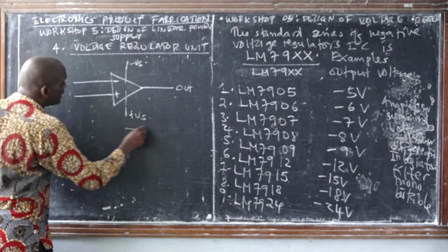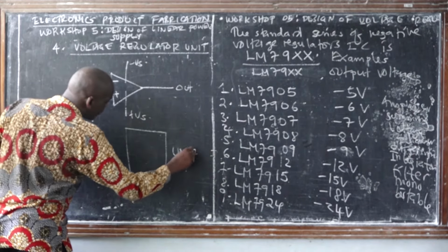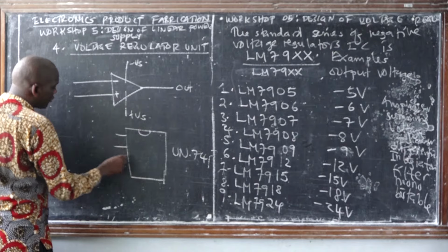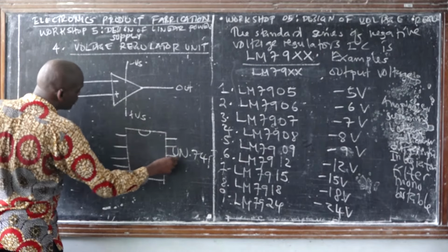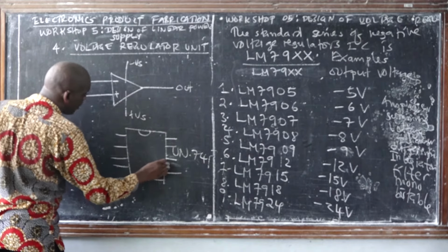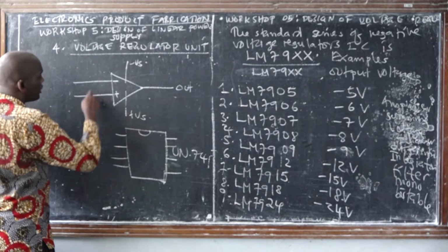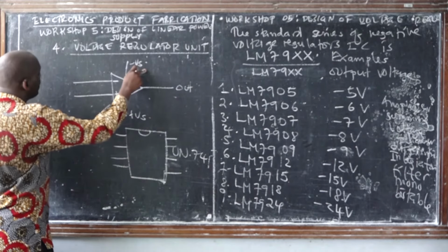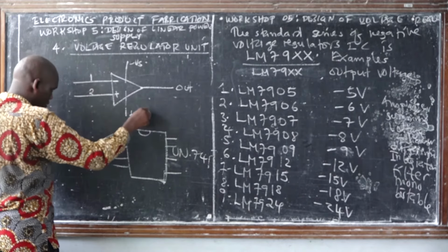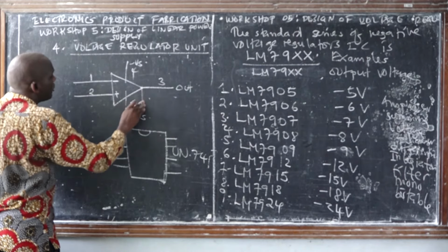Because the standard integrated circuit of an op-amp, for instance the 741, this is the simple operational amplifier, and this is the notch. It has pins. You can find that most op-amp ICs have more than one operational amplifier. So we have 2 pins for input, 1 pin for output. This is for the negative voltage supply, and this for the positive voltage supply. You can find number 1, 2, 3, 4, 5. But also you have some other terminals, which are 3.